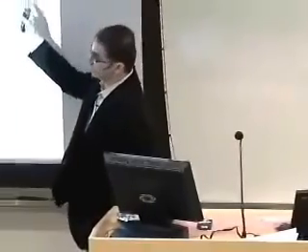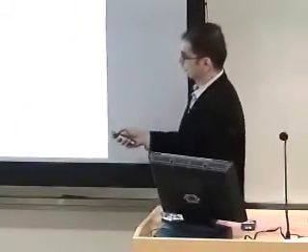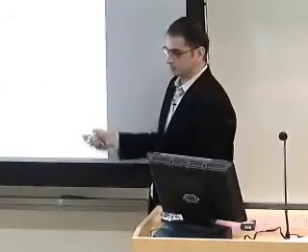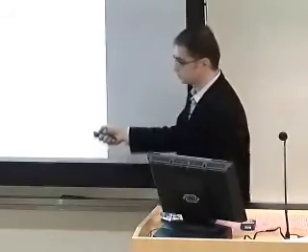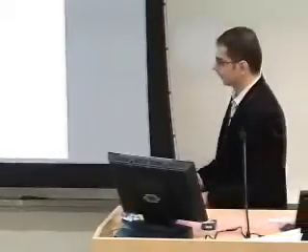Now, what happens here, and what I want you to notice, is that as we increase the number of bytes that we're actually sending, as we increase the payload size, two times are increasing: the time it takes to write the packet down to the radio and the time it takes to transmit the actual packet. This radio I/O communication can be up to 20% of the airtime. By simply considering the energy per bit in terms of power consumption and data rates is at least inaccurate in this case of the 15.4 radio.